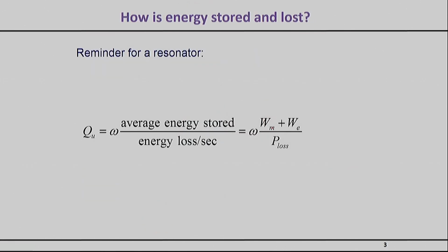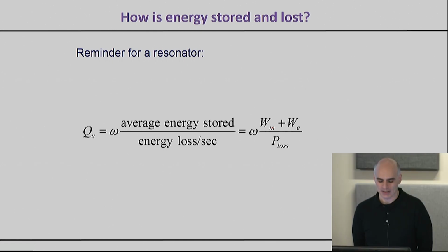So let me give you a reminder, first of all, of the true definition of the unloaded quality factor, which is the quality factor we're talking about here. As I mentioned before, and the equation is right here, the unloaded quality factor is related to the energy that you're storing in the resonator over the energy that you're losing from the resonator.